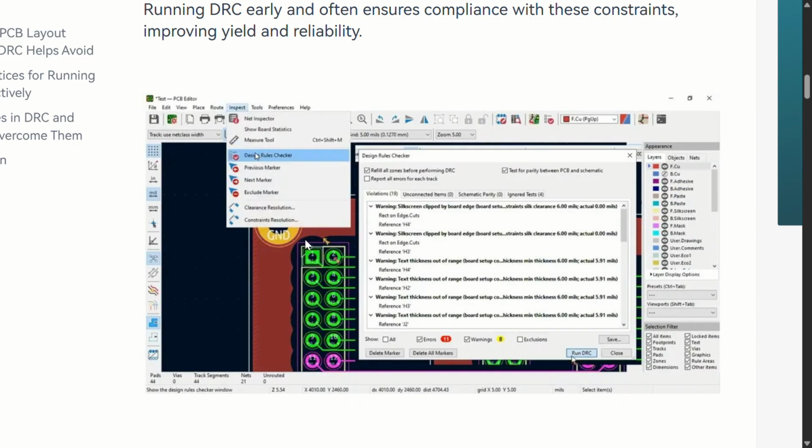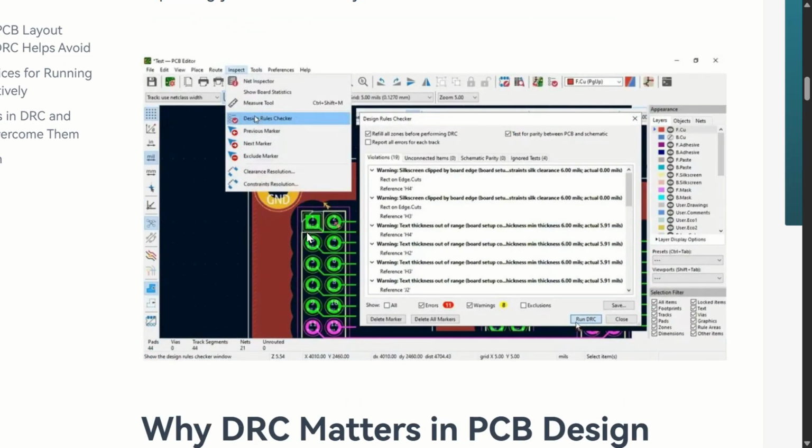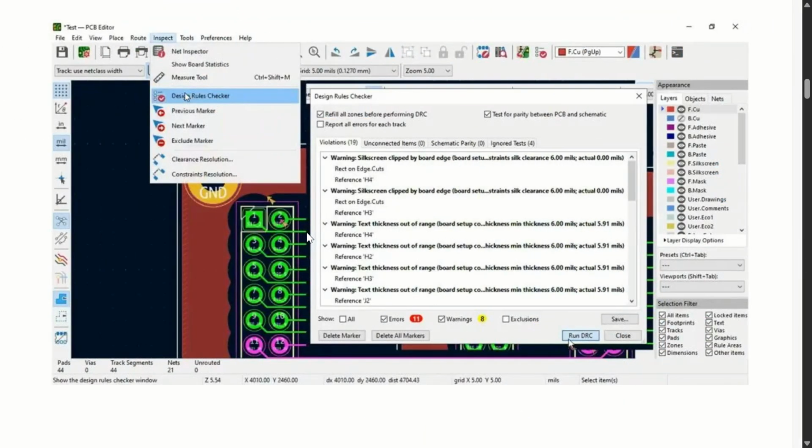All these rules cannot be explained in this curriculum, because we are just introducing PCB designing to new candidates. For different components there are different clearance rules, right? Between copper traces it's 0.15 mm. That is the minimum spacing, the minimum clearance.